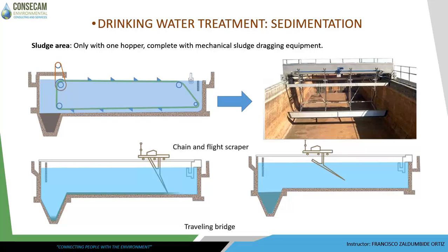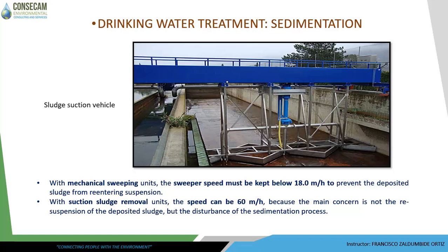The second piece of equipment is the traveling bridge scraper, which travels back and forth along a guide rail to drive the haulage blade. As the vehicle approaches the hopper, the blade drops and pushes the slurry into the hopper. When the vehicle moves away from the hopper, the blade lifts, and the cycle repeats. A third suction pumping mechanism can be used. It consists of a traveling bridge and a pipe with a suction nozzle that reaches to the bottom but does not touch it, so that by suction, the sludge is drawn upward through the pipe and discharged. It will also slide back and forth.